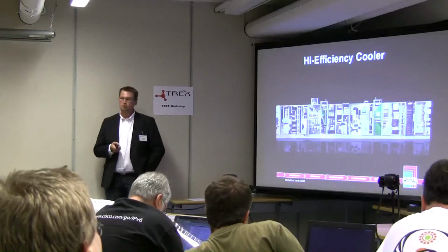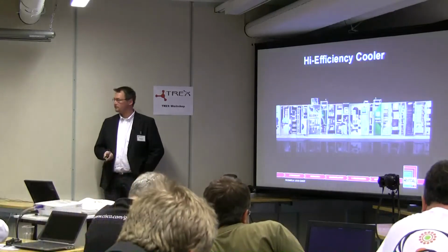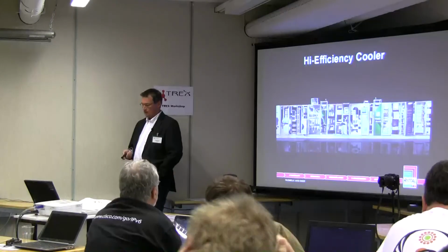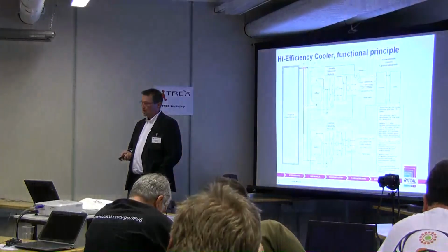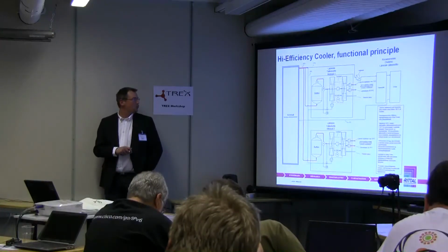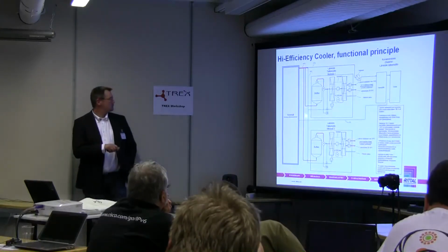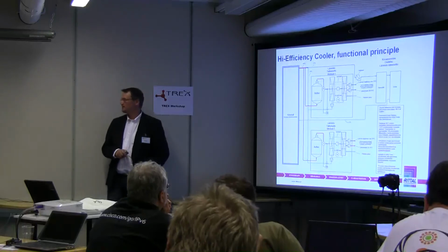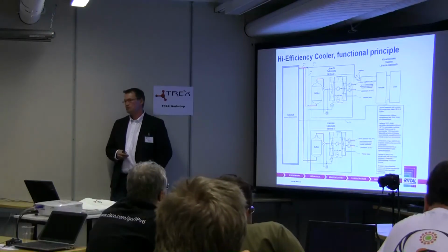Then the innovation that was promised. This is basically made by Rittal Finland. We have a person named Marko Ruokonen who has defined this next product. We are calling it a high efficiency cooler with heat recovery. The idea is to cool down the water from the data center. Here we have the inlet 7 to 17, hopefully closer to 17 than 7. And the water we get out from the data center is approximately 25 degrees, 20 to 25.